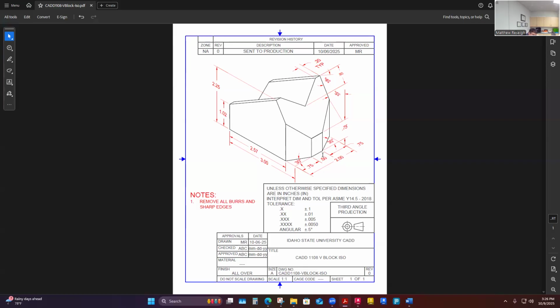If I was to do a right side view and look at this with my eyeballs on this surface here, I'm going to be able to see this rectangle in its true length form. It's perpendicular to my eyes, so it's going to be a 3/4 by half inch rectangle. And then this surface I'm going to see in my right side view, but it's going to be all foreshortened. It's going to be going up and away from me here, over to the front views and over to the back views. Everything's going to be foreshortened.